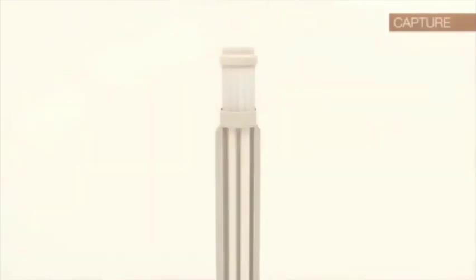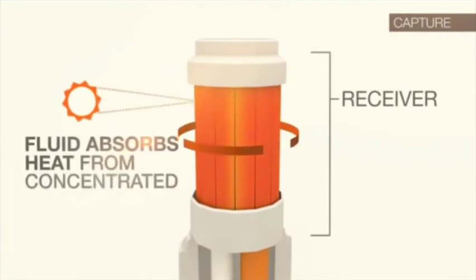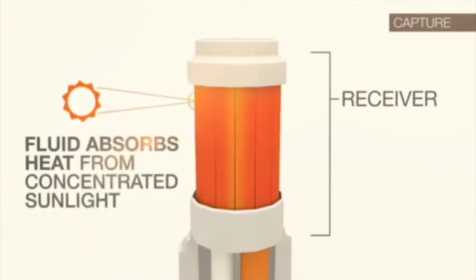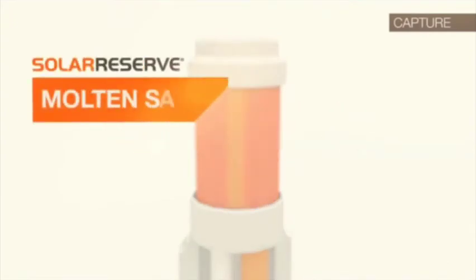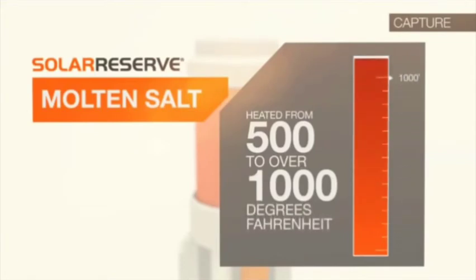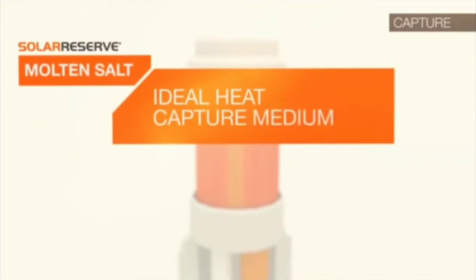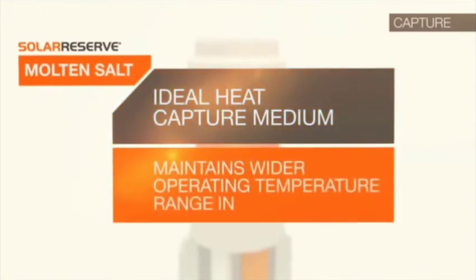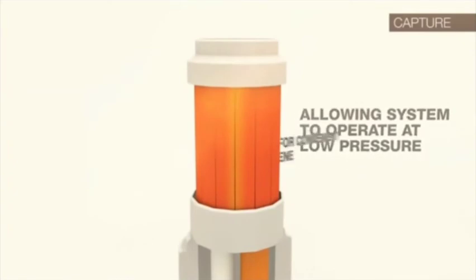Within the receiver, fluid flows through the piping that forms the external walls. This fluid absorbs the heat from the concentrated sunlight. In this technology, the fluid utilized is molten salt, which is heated from 500 to over 1,000 degrees Fahrenheit. Molten salt is an ideal heat capture medium because it maintains a wider operating temperature range in liquid state, allowing the system to operate at low pressure for superior and safe energy capture and storage.